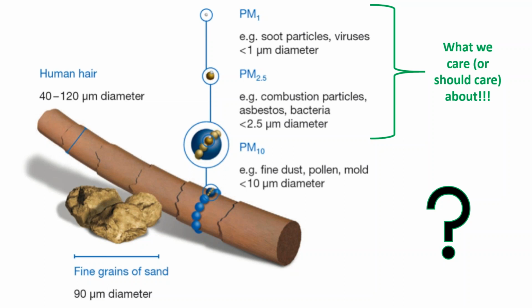So when we're talking about microbial size particles, as you can see, PM 2.5, particulate matter 2.5 micron or smaller, that's where you're going to hit 90% of your bacteria. As you get even smaller than that into PM1 category, you're going to see your viral vectors or your viruses. Now, this is really where we want to pay attention from a biosafety lab standpoint, because obviously if we're working with an experimental vector, it gets out into the public, we have a massive issue.